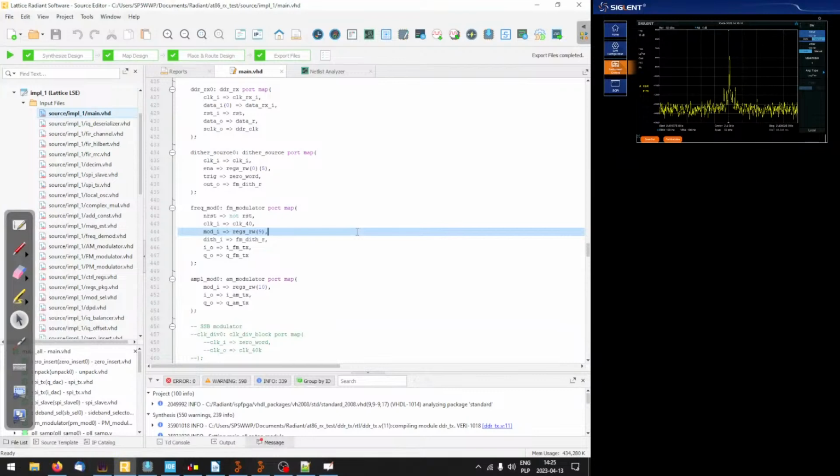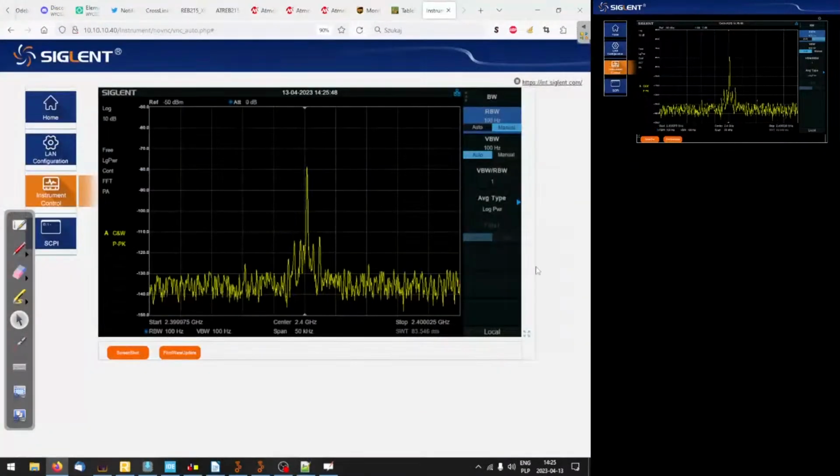And the CTCSS works in a similar way, but instead of checking what's the signal strength, you actually demodulate the signal first and then check if there is an inaudible tone within that signal. So you take a look at the baseband and see if the tone is present. If the tone is present, you just unlock the squelch, and the tone frequencies are below 250 hertz, I believe.